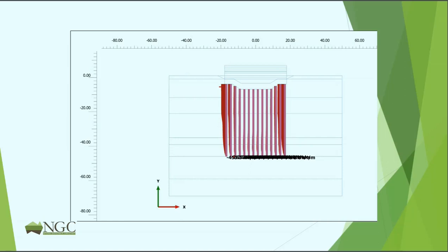You can see that these piles at the edge are carrying a lot of load, and these piles in the middle are carrying very much less load, exactly as PIGLET was predicting, and not what you will get from a linear elastic spring on a rigid base model, because all of this block of soil and piles is going down together. Therefore, you're not getting relative movement between the pile and the soil in order to generate shaft friction to support a load. So the load goes to the edges where there is more relative movement.